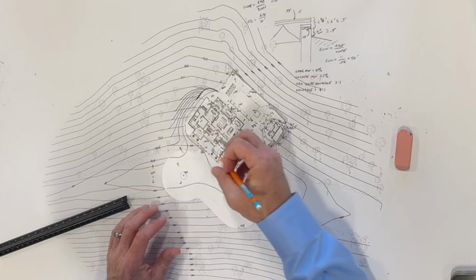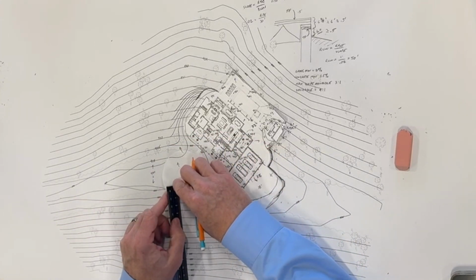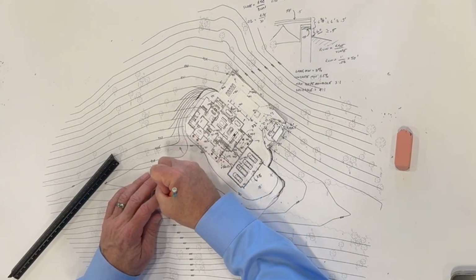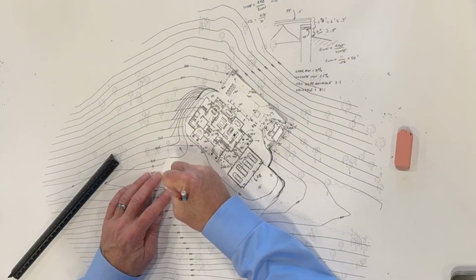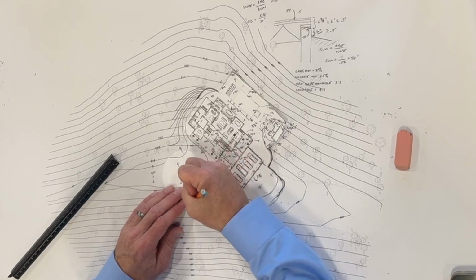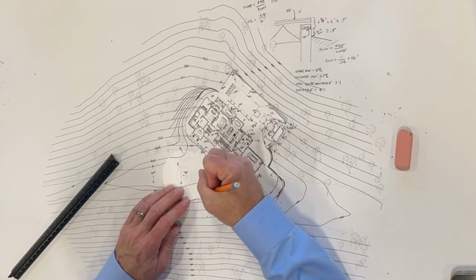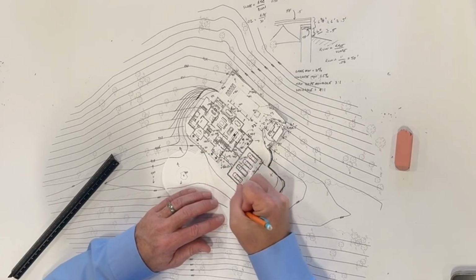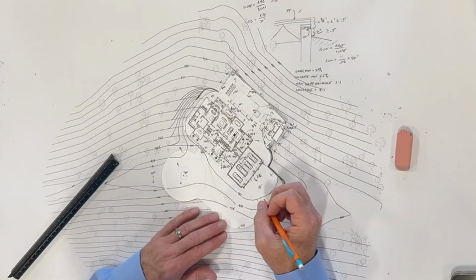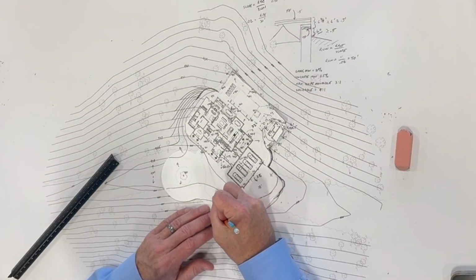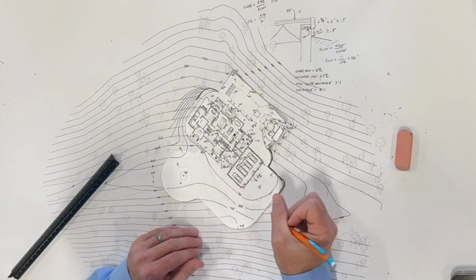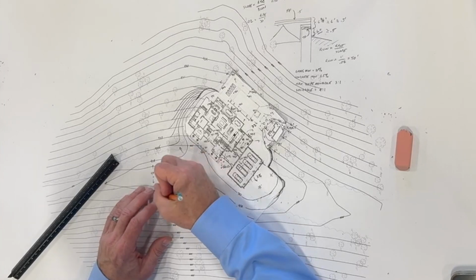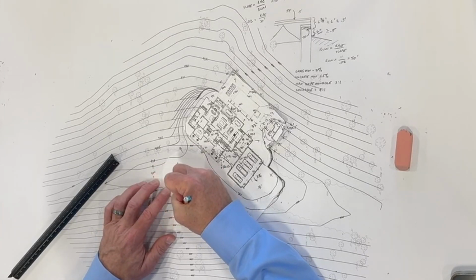So that means the 938 has to go there. Here's the 938. And we know that has to be at least 12 feet. And really, you don't want this driveway, you kind of want the roundabout to be pretty flat. So I'm probably going to bring the 938 around that, and then come across this 938 there. Same thing with 937. It can really just kind of come through here, where it can go like that, right? So there's a 937, which now has to come down, and we'll make this a 3-to-1 so we can get that close.